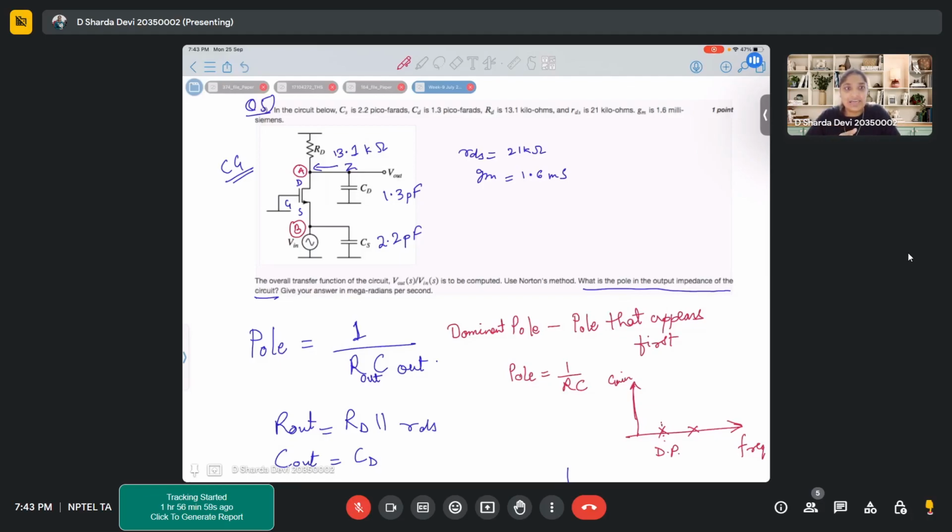Is there any other doubt? No, madam, these capacitances are defined by two conducting plates separated by a dielectric. See, that is only possible when you have parallel plate capacitor behavior, right? But in the case of a junction, there also we ultimately consider that the depletion region is devoid of charges, and there are charges only on the two sides of the junction, and then we calculate the capacitance.